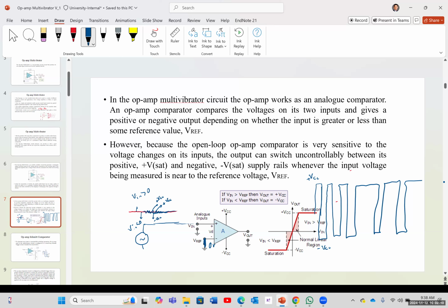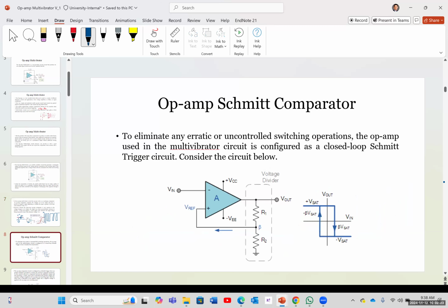And sometimes those signals, especially for this system, are low frequency. If you connect the capacitor in series, it's going to create a high pass filter, so it's going to block all the inputs that we have. Another option that we can use is simply to give it a feedback. Feedback always makes our system stable.